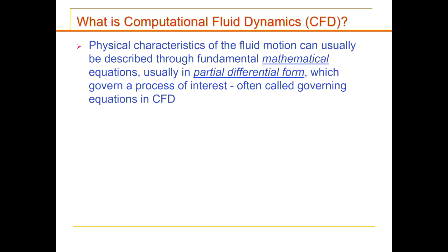So if you have 100 kilograms per second coming in, you must have 100 kilograms per second going out. Nothing can be created in the middle, okay? Mass conservation, right? And even from the computational approach itself, you can check your mass error. Your mass error has got to be very, very small because you cannot create more mass. If you create more mass, it means there's something wrong with your solutions. Okay, that's something to check as well.